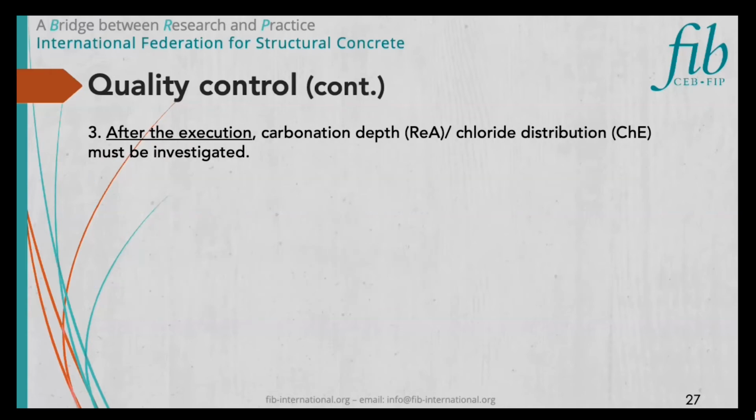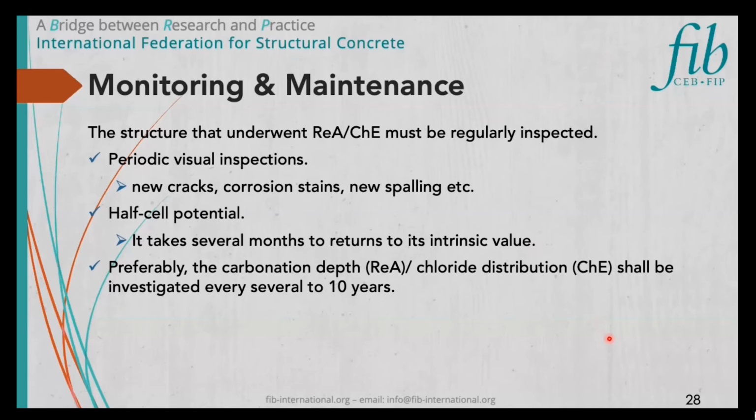After the execution, carbonation depth or chloride distribution must be investigated in order to check if the designated repair was achieved. This page describes the key points of maintenance that must be carried out after the execution of repair.